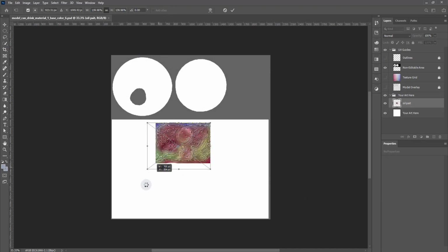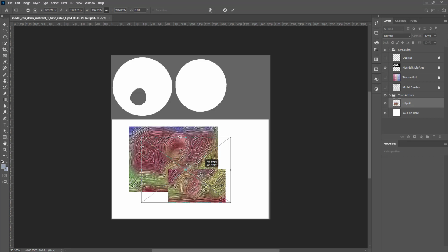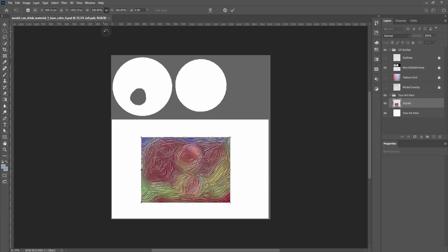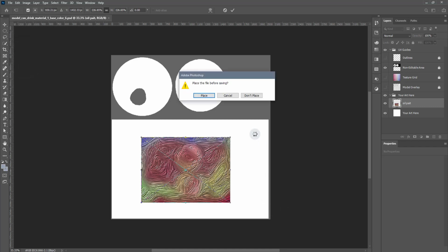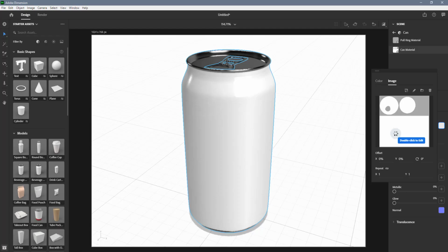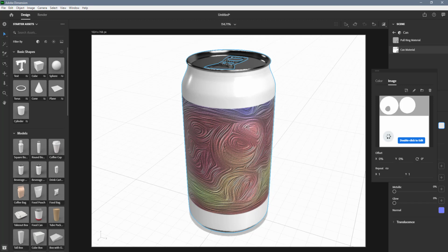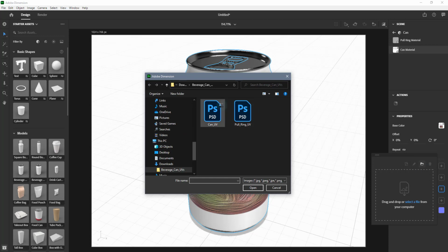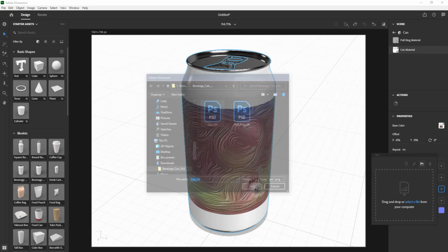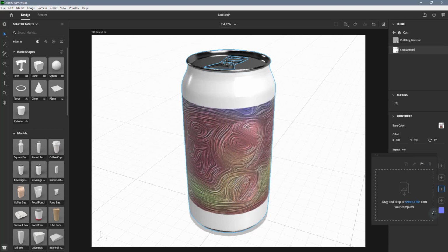Reapply the image onto your 3D model as a graphic layer with the mode set to fill. Graphic layers will have their own material properties like metallic and roughness. Apply graphic. You can also reapply the image directly into a material property, such as base color or any of the material properties. The image will only apply to that property.